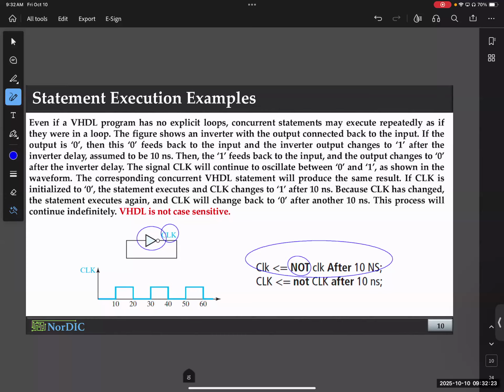We'll talk about sequential circuits pretty soon, flip-flops and latches, and they are driven by a clock. So basically, when the clock is high, something happens. When the clock is low, you just stop and wait. You take turns to work, essentially. So the clock signal is a very important part of chip design. You basically have dedicated clock generators on chip.